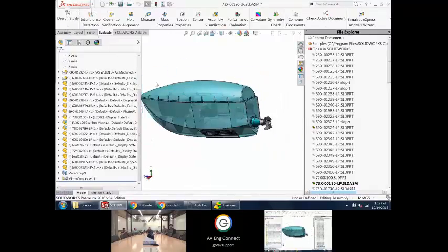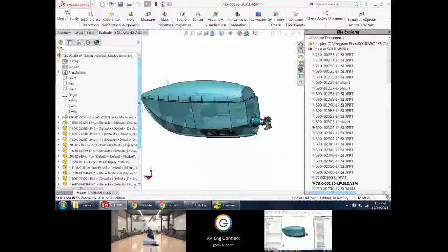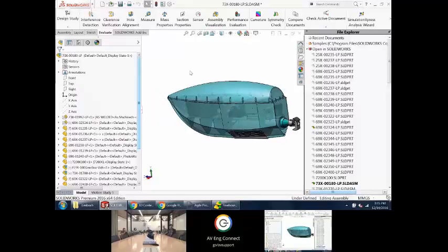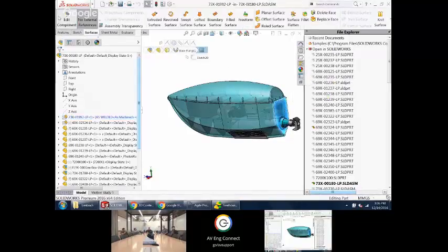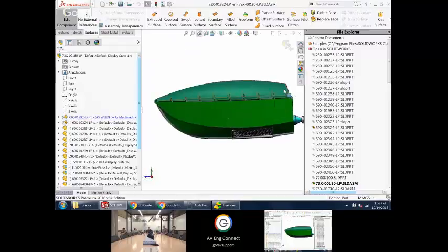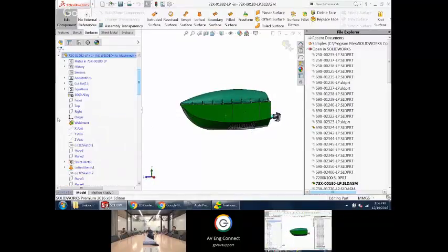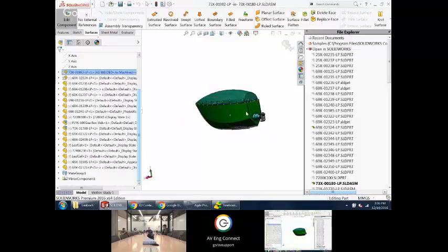Let's talk about in-context design. There's a couple of ways to do in-context design. One, I showed you a long time ago when I was playing with those valve covers in the radial engine. I can actually make it taller and smaller in the assembly. That's in-context design. I'm just changing a dimension at the assembly level. But a more intrusive type of in-context design comes with this edit component choice. If I select on a part and choose edit component, I'm working in this part, you'll see the one that turned blue, at the assembly level.